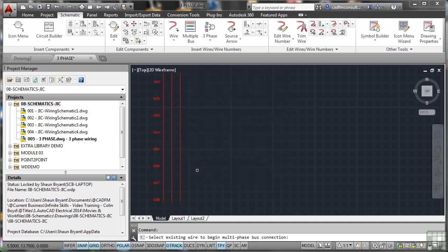We click on OK. I'm going to select this wire here, click, and as I drag outwards, there's my wires. I'm going to take them quite a distance away, about there, and click. Now you'll notice Snap and Grid have come on. I'll just press Enter to confirm those 3 wires first though. I might switch off Snap and Grid for the moment, just to make life easier as I move around. I'll put them back on maybe in a minute.